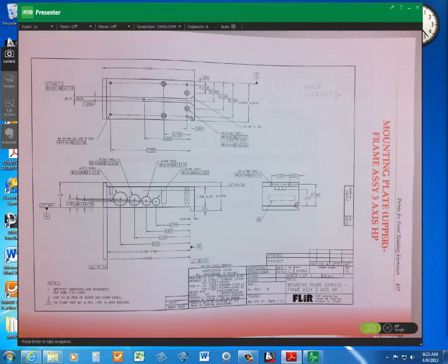So as soon as you see the circle M, you know what your position tolerance is going to be at max material condition. It's next to it, okay? That calculates it automatic. Then, as we produce different sizes up to LMC, we're allowed to increase. So in your little chart there, it jumps 1/1000, then it jumps 2, then it jumps 1. So you just add it to it, okay? So your next size would be 8/1000. Then for 0.190, it would be 10/1000. Then for 0.191, it'd be 11 thousandths.